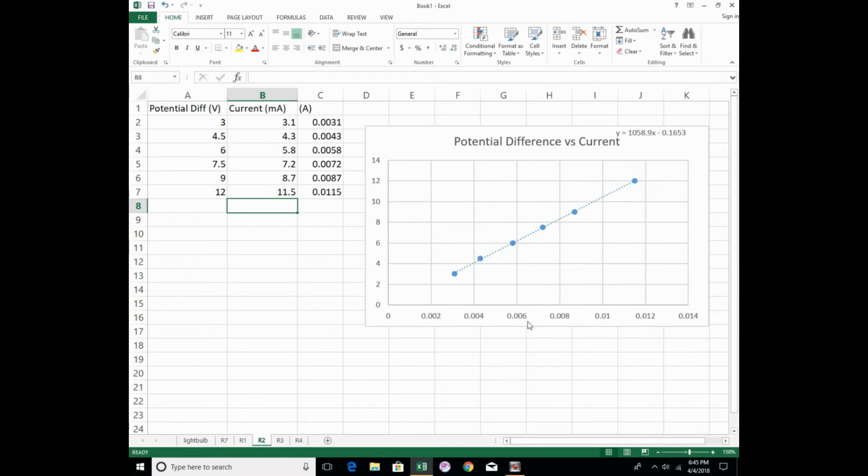All right, the next one was a 1,000 ohm resistor. Well, that one is right at about the 5%, give or take. We're a little above, but we've got 1,058, 59, so about 1,060. So we're a little above. It's possible that my equipment might be a little bit off. That being said, we can see a nice smooth line, and our slope is about 1,000. This is a 1,000 ohm resistor, or at least that's what it's spec'd at.